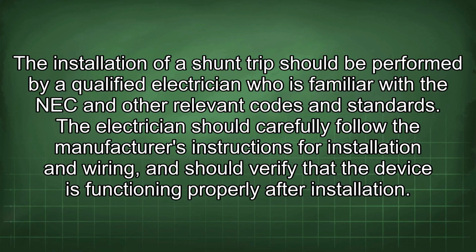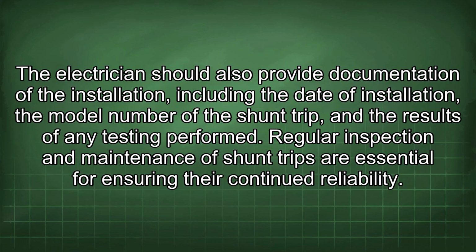The electrician should carefully follow the manufacturer's instructions for installation and wiring, and should verify that the device is functioning properly after installation. The electrician should also provide documentation of the installation, including the date of installation, the model number of the shunt trip, and the results of any testing performed. Regular inspection and maintenance of shunt trips are essential for ensuring their continued reliability.